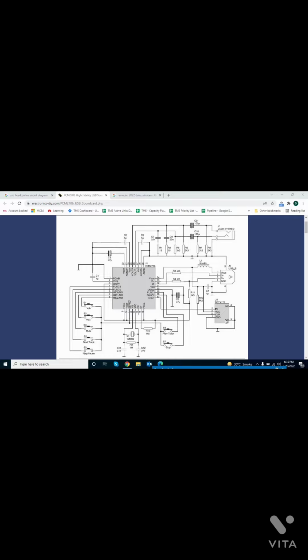This EPROM stores the data, and ground is commonly the output ground. And when you push these switches, they connect to ground. One terminal is common to ground, another terminal goes to pins 8, 7, 6, 5, 4, 3 and 17 and 18, which can give one-by-one signals, meaning volume down, volume up, mute, next, play, pause, back or stop.